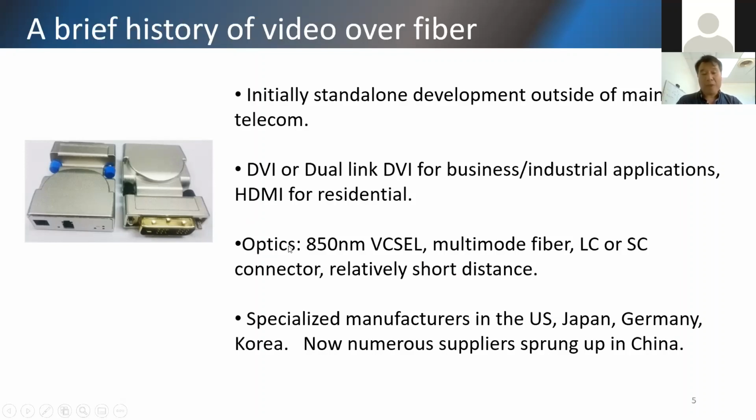In terms of actual optics inside these packages, we predominantly used 850 nanometer based VCSEL devices. This is a laser source, very commonly available, typically designed for multimode fiber, uses an LC or SC connector. I think this is an LC connector, and relatively short distance.